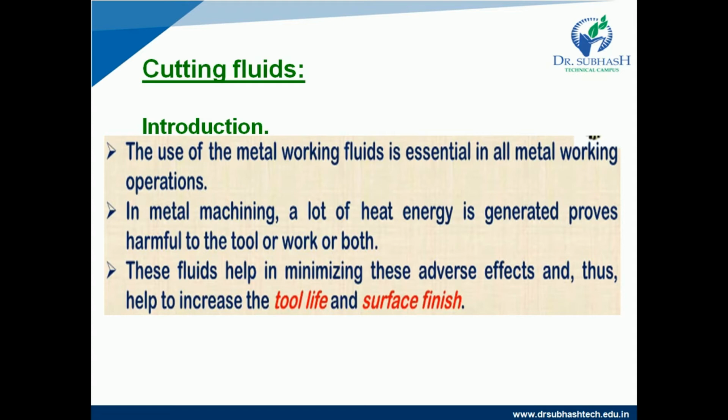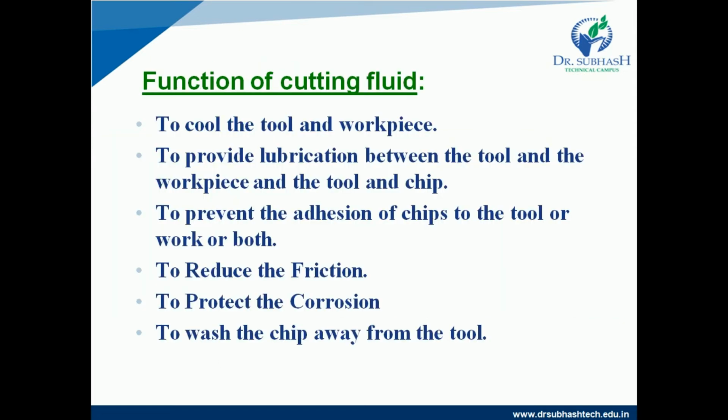These are the functions of the cutting fluid. To cool the tool and workpiece. If we are using the cutting fluid, then it will help to cool the tool and the workpiece. To provide lubrication between the tool and the workpiece, and the tool and the chip also, because it acts as a lubricator, right?